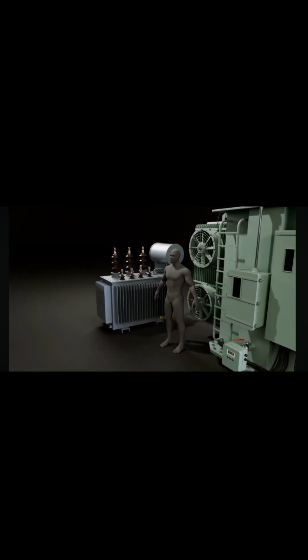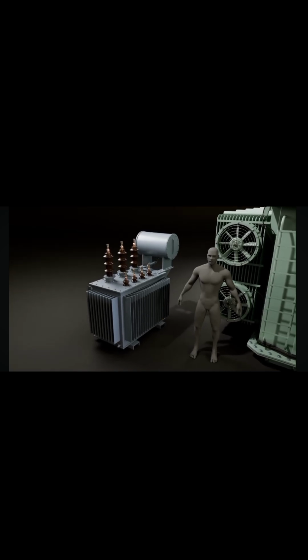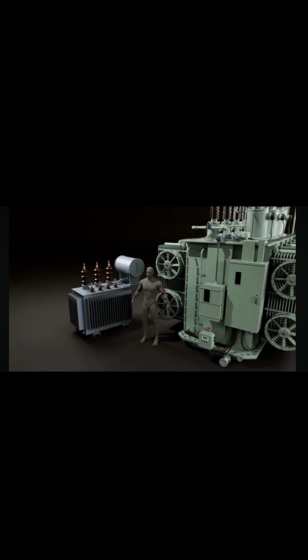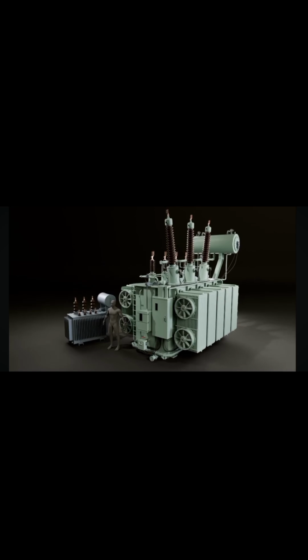In contrast, three-phase transformers are used for high-power applications. A three-phase transformer operates on a three-phase AC supply, which consists of three individual phases with a phase difference of 120 degrees between each phase. The power ratings of three-phase transformers can reach hundreds of MVA, depending on the specific transformer and its design. High-power rating transformers typically work on a three-phase supply instead of a single-phase supply, because three-phase systems are more efficient for transmitting and distributing large amounts of power compared to a single phase.